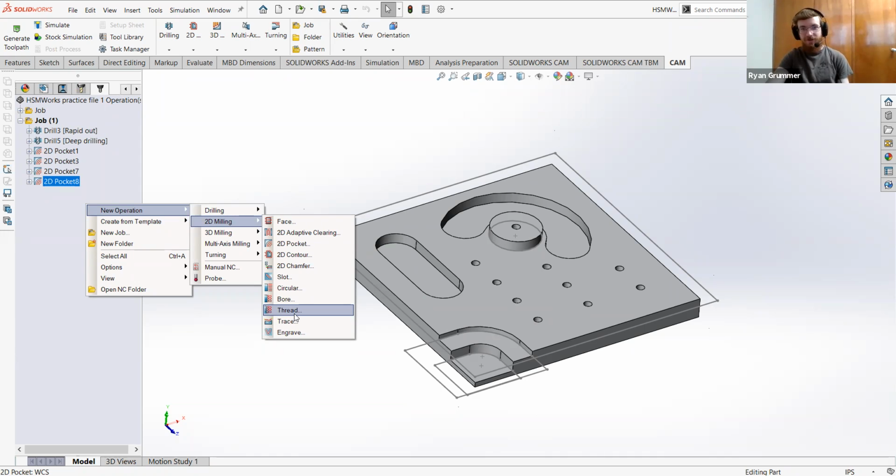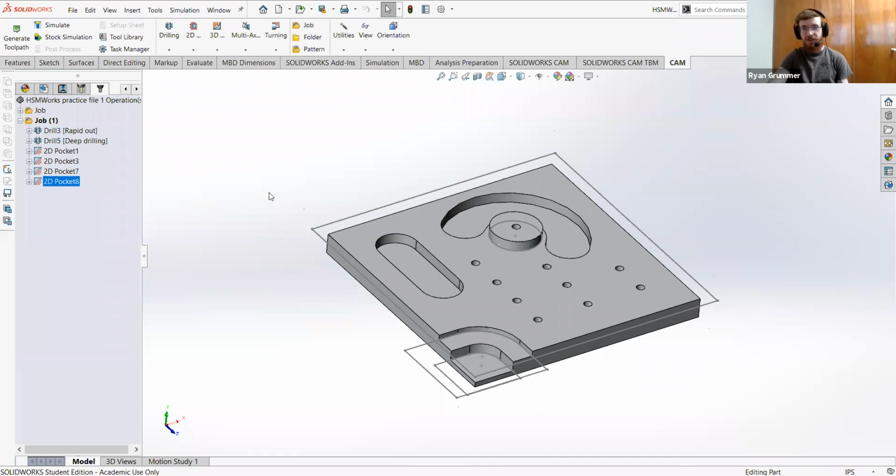So can you also import multiple parts to work on at once for a single sheet? Yeah, so in the guide, it actually tells you what to do there. If you want multiple parts that you're trying to make out of one sheet, you put them all in an assembly, arrange them where they need to be with some space in between them, and then you can save an assembly as a part.